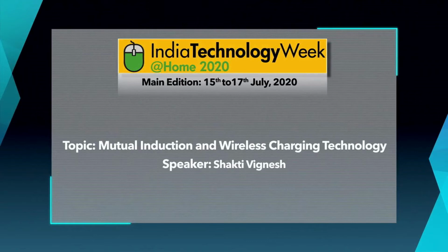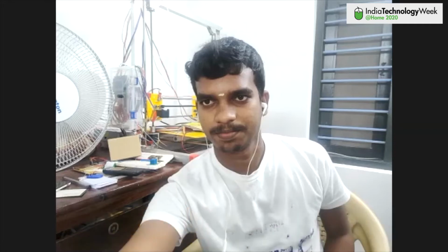In mobile charging, a mobile normally requires 5 volts, and the current depends upon your battery mAh. So you can provide 5 volts to the transmission end, and take another secondary coil wound with 7 to 15 turns and bring it near the transmission end. You can produce the required EMF for mobile charging.